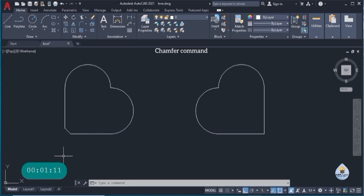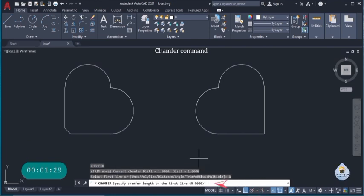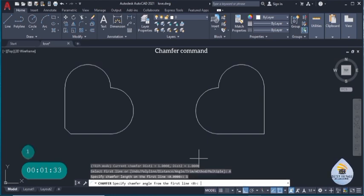Let's try that command again. I'll type CHA, enter. It's telling me to specify. I can click on distance, I can click on angle. If I click on angle, it tells me to specify the length first. I say okay, 1, and click enter.